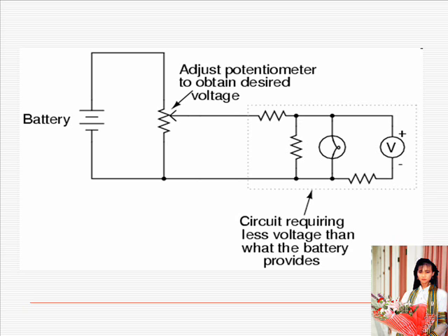In other words, if the potentiometer knob or lever is moved to the 50% exact center position, the voltage dropped between wiper and either outside terminal would be exactly 1/2 of the applied voltage, no matter what that voltage happens to be, or what the end-to-end resistance of the potentiometer is. In other words, a potentiometer functions as a variable voltage divider where the voltage division ratio is set by wiper position.